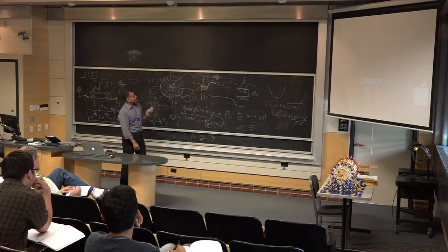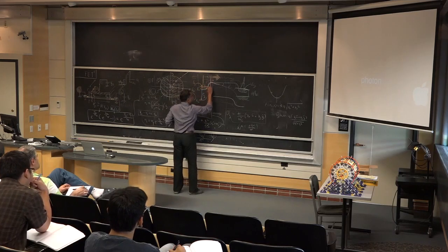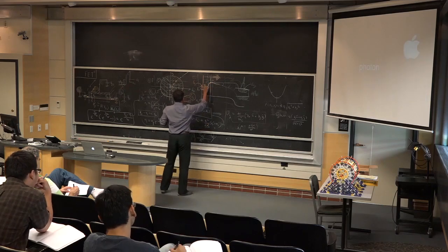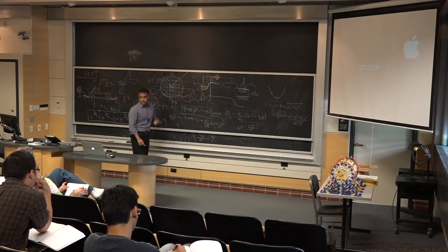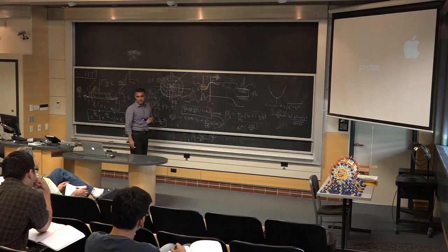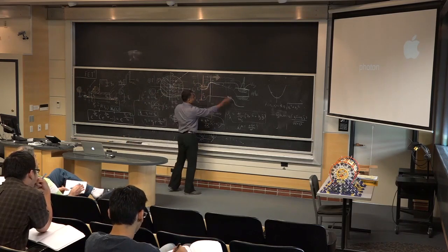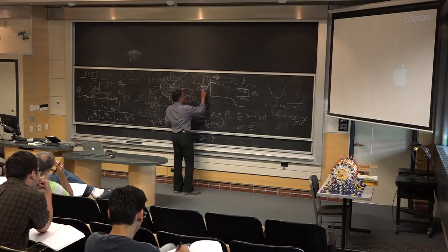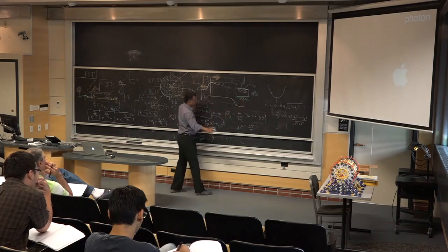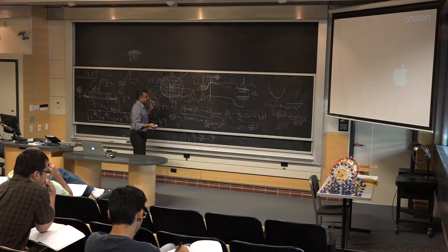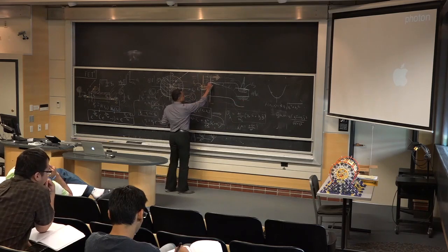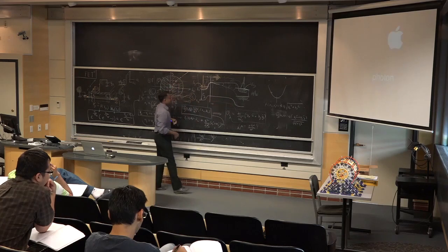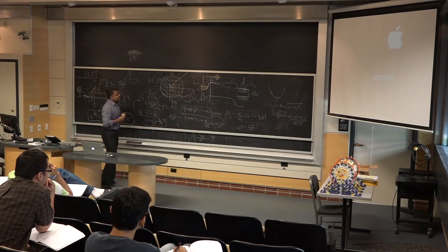And that plane is called the source injection point plane. What we're going to do is ask the question: what are the carrier densities at that injection point? That's a unique plane here. You can see that it has to be a unique one, because every other point which has a flat band is in a region in equilibrium with different things, which is not capturing the whole picture, but that point is capturing the picture of what's happening from both source injection and drain injection.